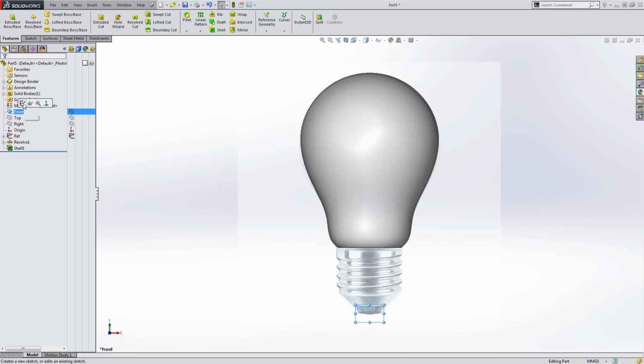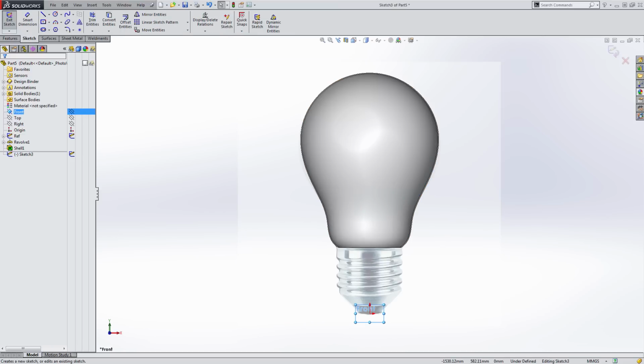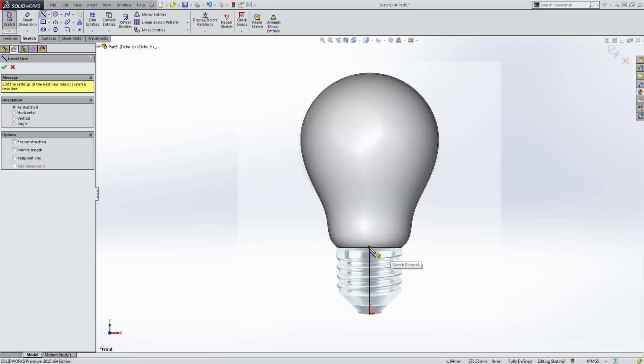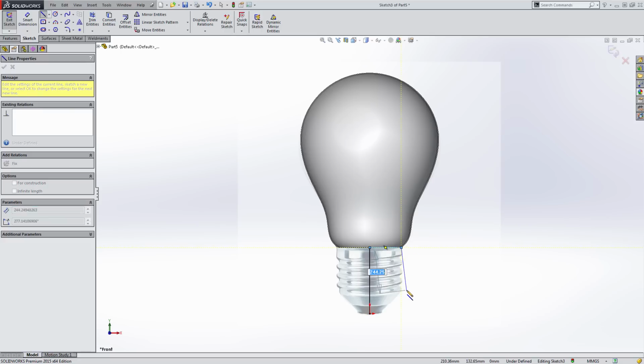Next, we're going to do a secondary sketch on the front plane. Now remember that our reference, in this case in sketch 2, we can go ahead and show that. We're going to take this line and use convert entities and just bring it into our current sketch and then hide it again. So now that we know that we're going up to the appropriate edge here, we can draw some more reference lines. We're going to come over, down, and we can taper over. I'm going to add a little bit of a step here, taper down, and come back over.